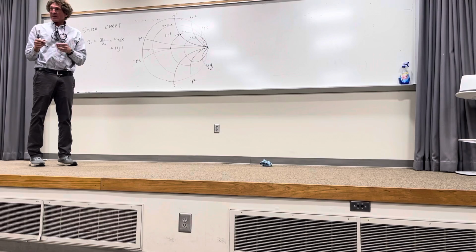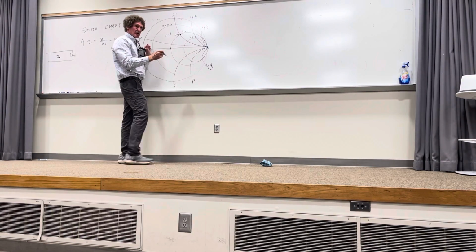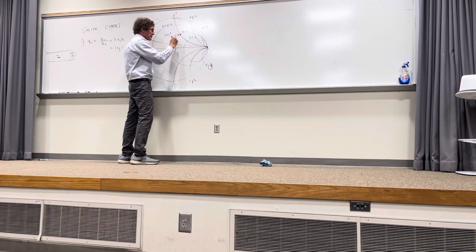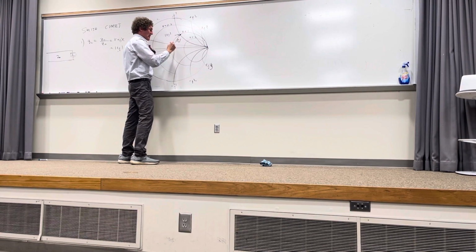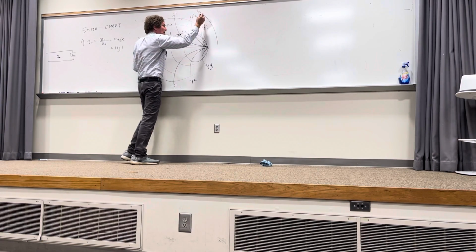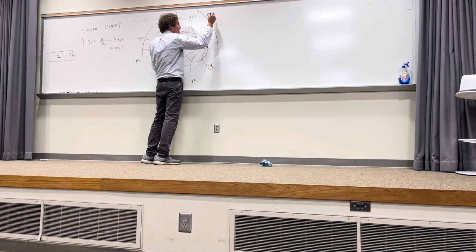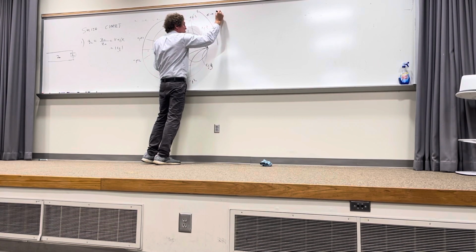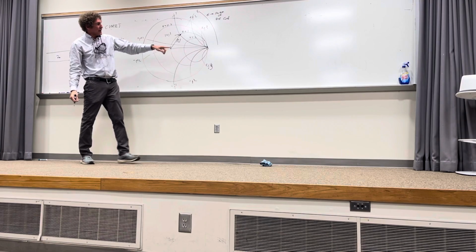So why are we doing that? That's a good question. Well, this is where it gets interesting. For starters, what this represents is something of magnitude of the reflection coefficient. And the angle of the reflection coefficient, if you look at your Smith chart, you're going to see out here an angular measurement in degrees. And this will be the angle of reflection coefficient.